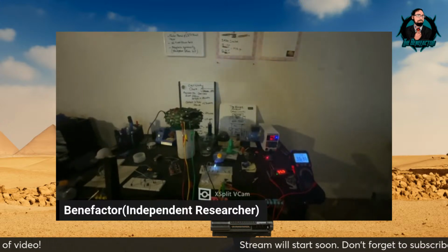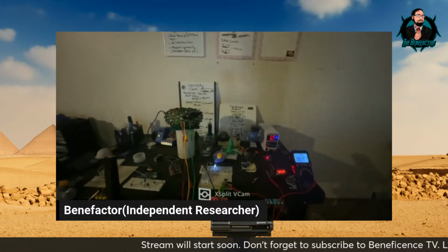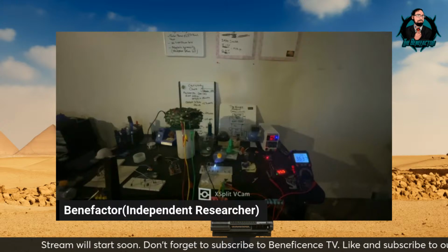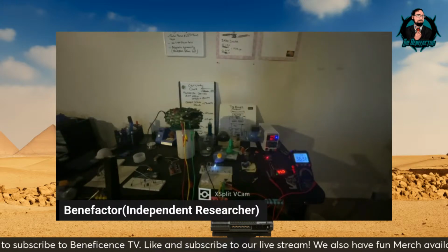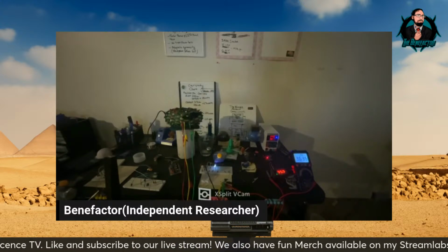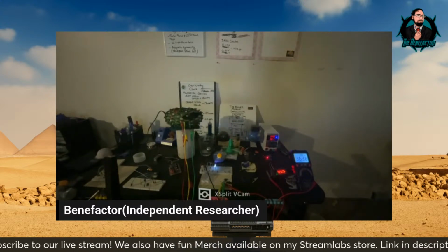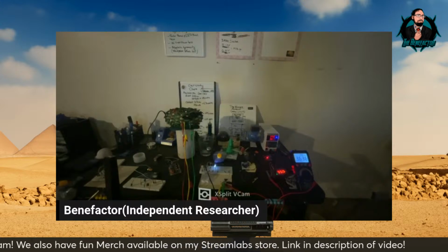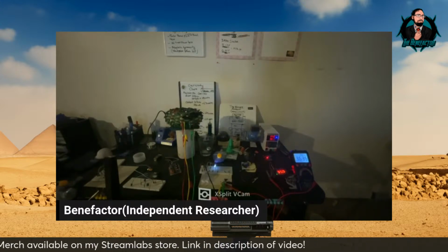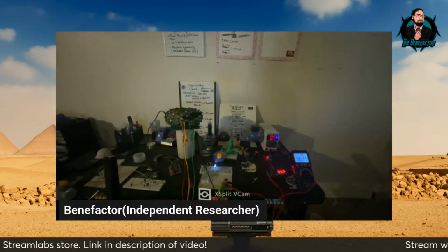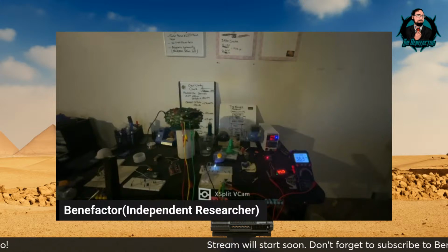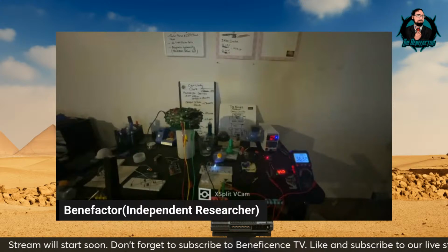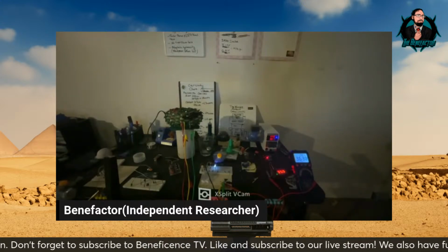I know you're talking about programming, but regarding the neodymium sphere, I don't think it's going to be doing much unless I can get the frequency lower than 1 kilohertz, which is the minimum for the PWM. If I can hook it up to the circuit, though, to restrict that frequency and draw it back a little bit, maybe with a capacitor and a resistor, we might be able to bring it down. But I don't know if I have enough capacitors and resistors for that. To get the effects that I was seeing, I had to get really low, like below 20 hertz.